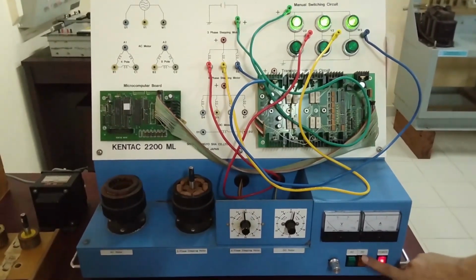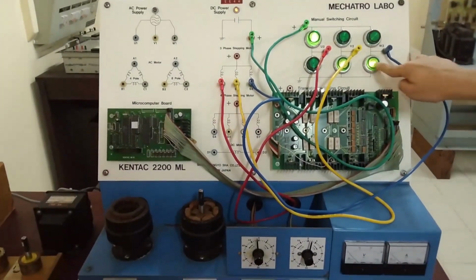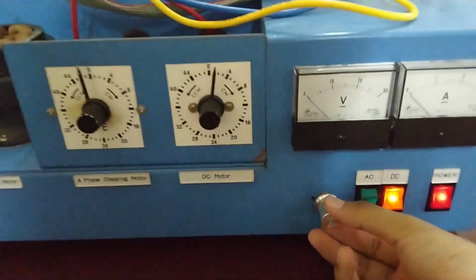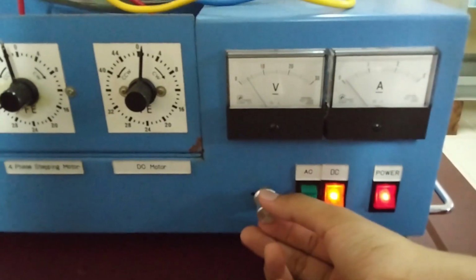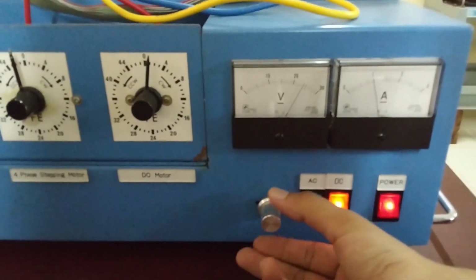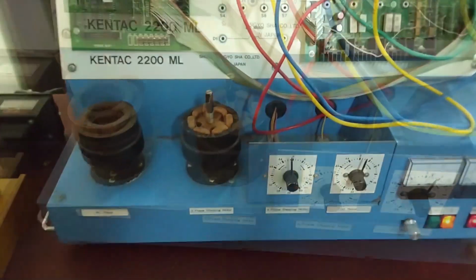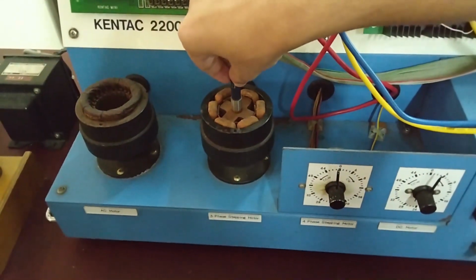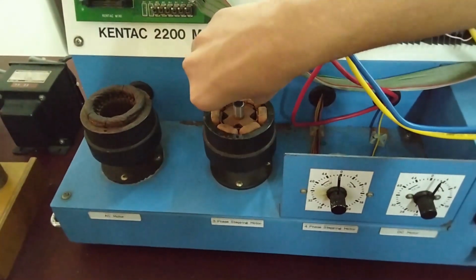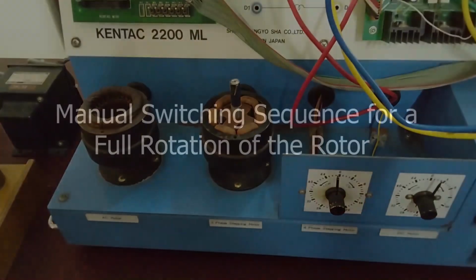Let's turn on the main switch and the DC supply and then energize only one phase using the manual switching circuit. Then we have to turn the dial to adjust the current to 1 ampere. Now let us have a look at the rotation of the rotor. When we try to rotate the rotor, you can see that there is a restraining torque for its motion.